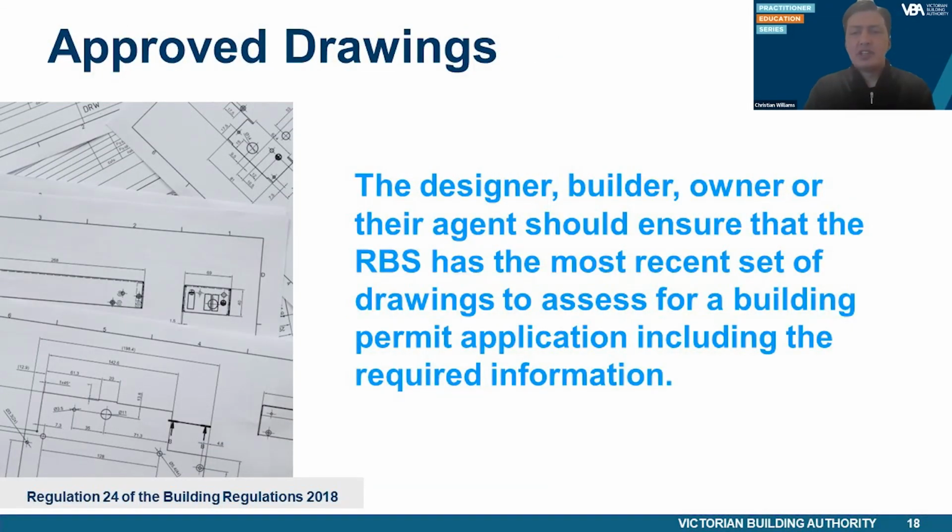One of the major considerations for building permits is the approved drawings. The designer, builder, owner, or their agent should ensure that the RBS has the most recent set of drawings to assess for a building permit application. When undertaking building work, practitioners need to ensure that the documentation they are using and/or providing are the applicable versions and have evidence of approval stamped and endorsed on them by the RBS.